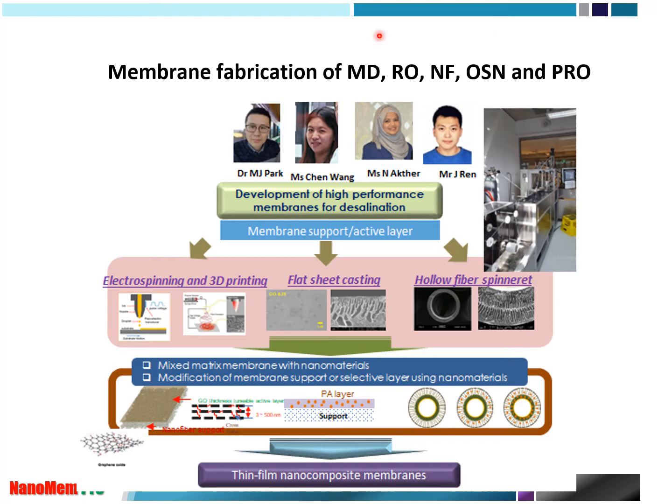Especially the drop on demand inkjet printing is a promising approach, allowing the patterning of materials with negligible material waste. Hence, the significant reduction of raw materials cost can be achieved. Furthermore, inkjet printing can be easily adapted to a roll-to-roll process, which is suitable for large-scale application.